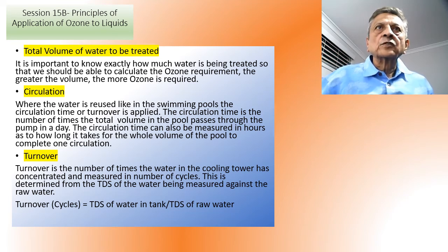It is important to know exactly how much water is being treated so that we should be able to calculate the amount of ozone that is required. The greater the volume of water, the more ozone we have to apply.